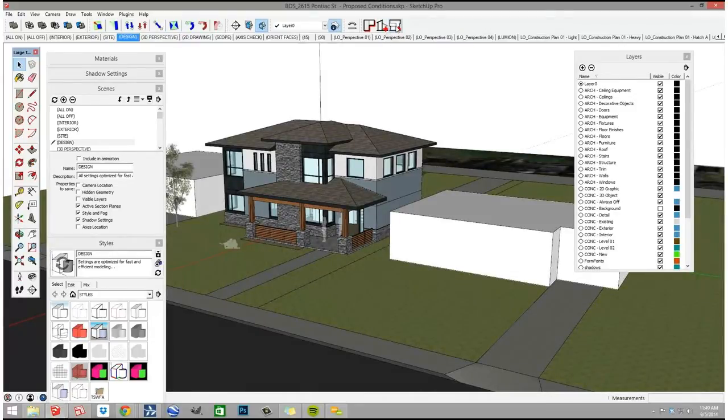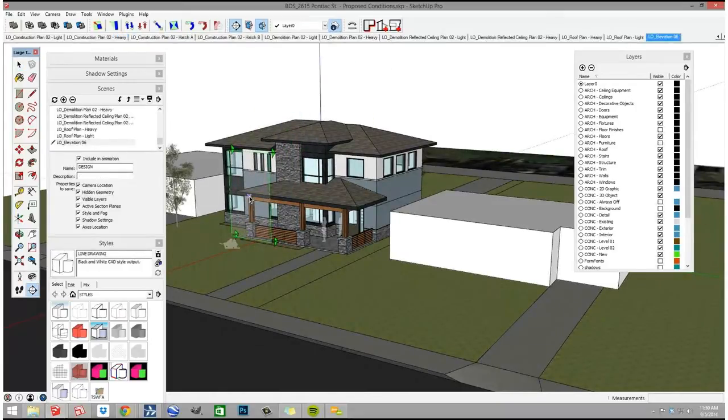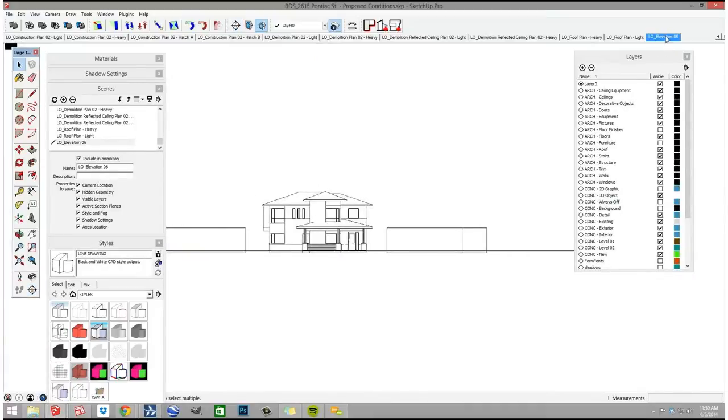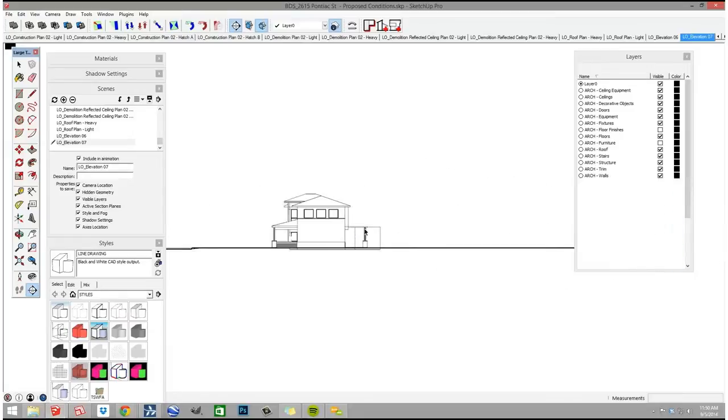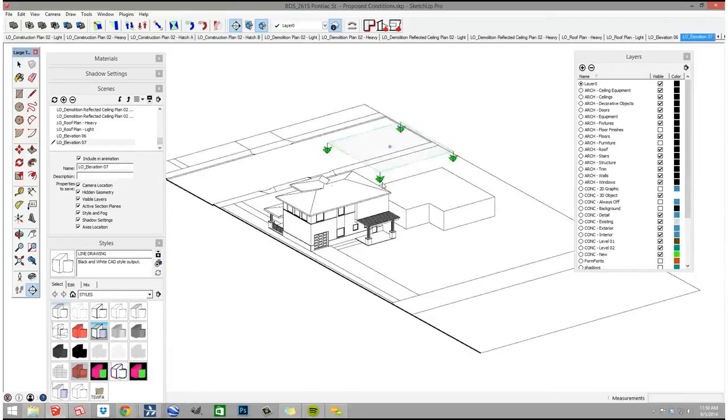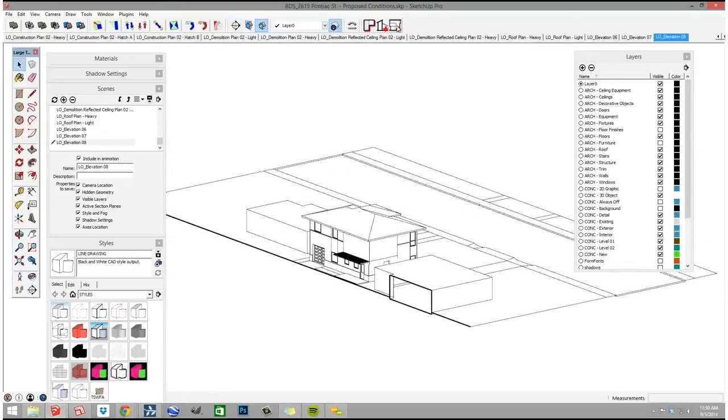So watch this. I activate the tool. I just put it on the front elevation and click. And now it renamed it Elevation 6. The reason it did that is because we already added elevations and deleted them. No big deal, we'll just go back and rename those. So what I'll do is orbit around, add another elevation right here. God, that is so cool. Add an elevation right here. And then add one more elevation right here.